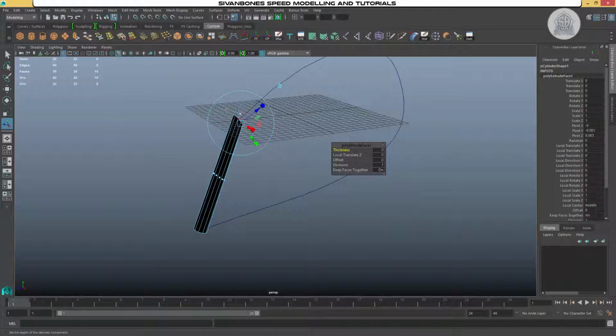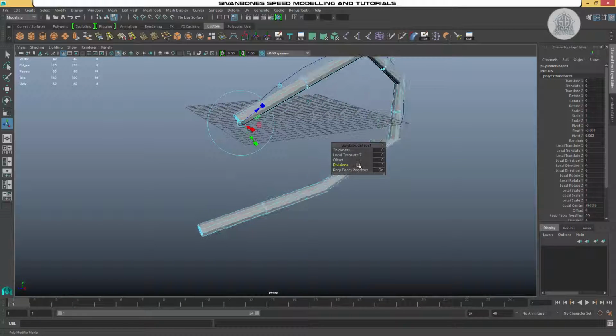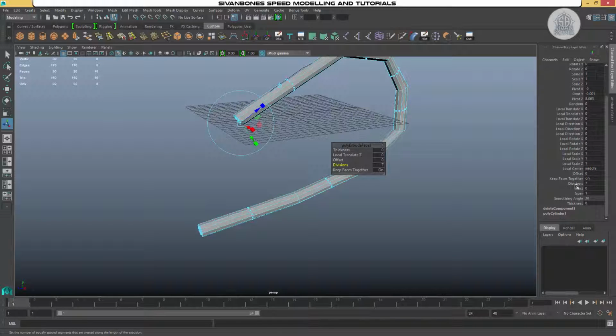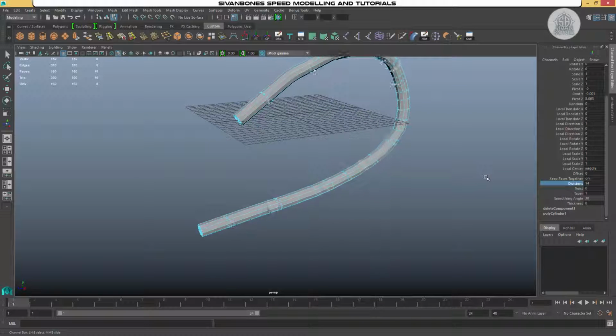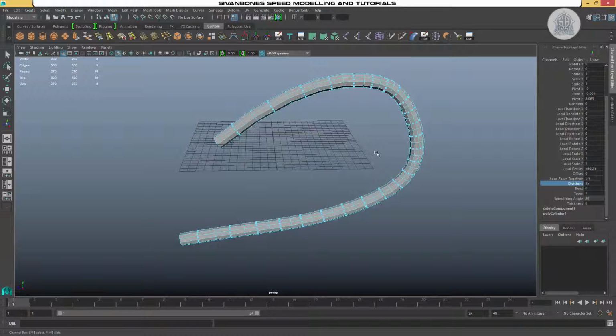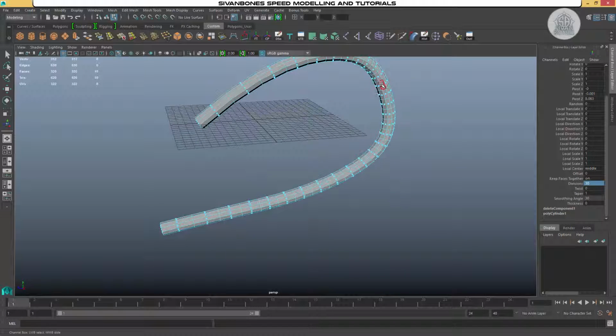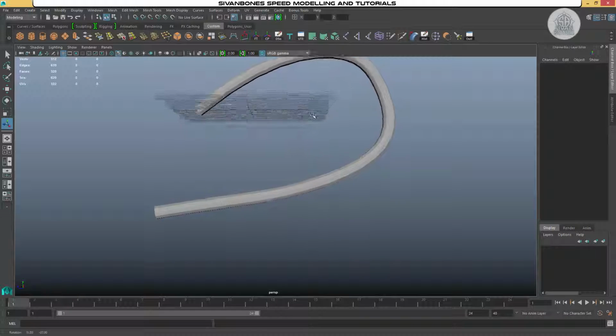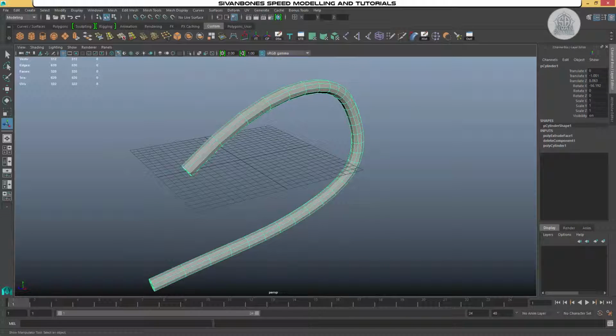And then what it will do, like I said, is just jump straight to the end. So the next thing we need to do is increase divisions. Depending on the version you may not have this box, so it's on the right, you scroll down and there's divisions, so we can click it and middle mouse drag. So you increase the divisions till you're happy. It will only drag to 25, but you can set it as high as you want. You just have to type the values in. So that's a standard extrude along a curve.